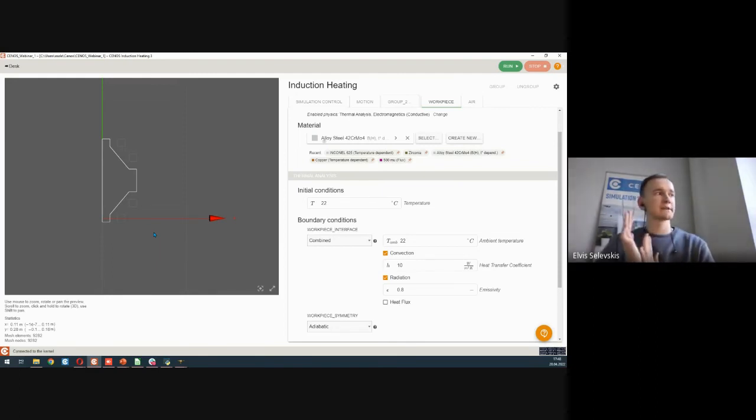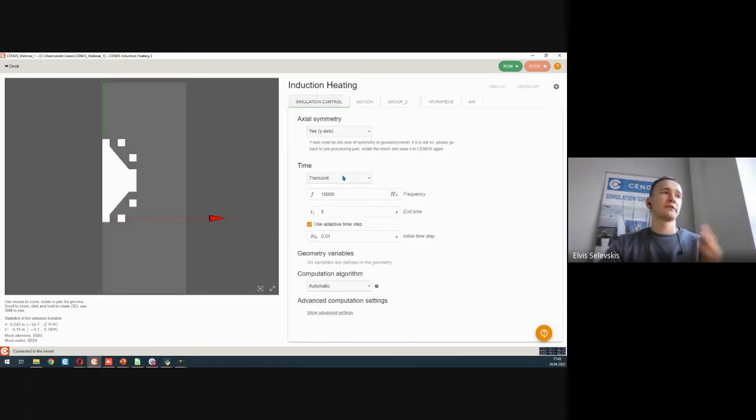For the case which I set up, the temperatures were exactly the same. The only thing which might have altered them, like 1 or 2 or 3 degrees, might be that the mesh was rougher in the 3D case than in the 2D case. But if you have a full 3D case, or a slice geometry, in case of a slice 3D geometry, the results should be quite close.